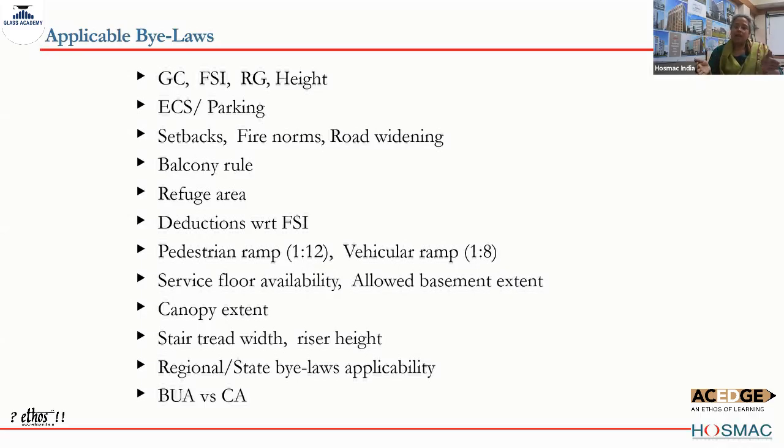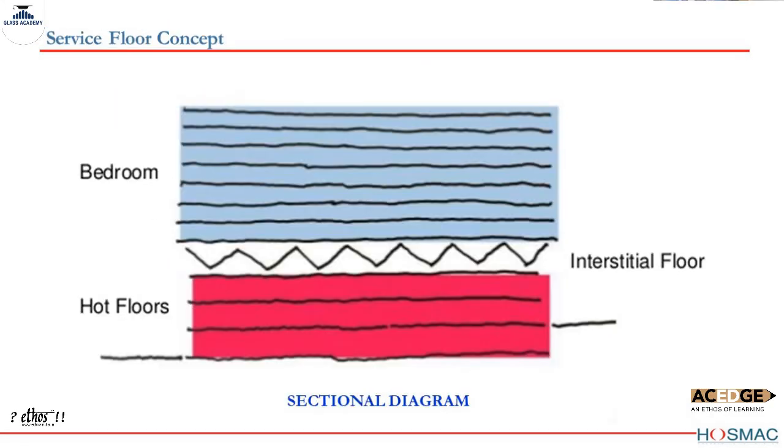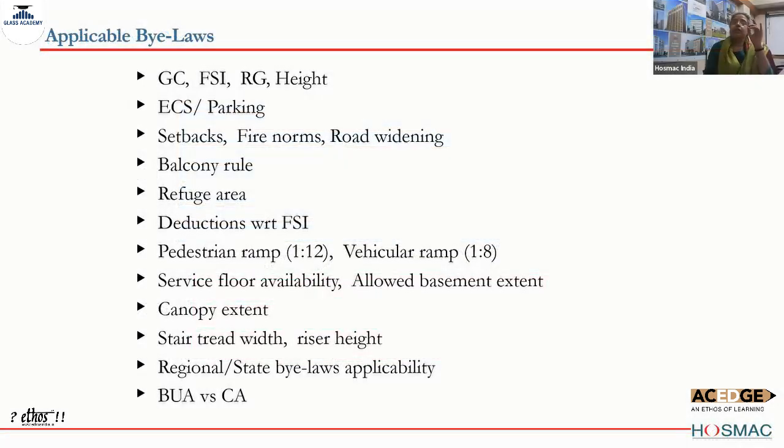So this forms part of the podium floor, which is the lower floors. Above this comes the service floor, just one floor, and beyond the service floor, even if it's 2 floors or 10 floors, is the inpatient department, which is housing. So what I'm trying to say is there is a D&T, there is a service floor, and then on top is the inpatient housing. So the downtakes of the inpatient toilets culminate at the service floor.